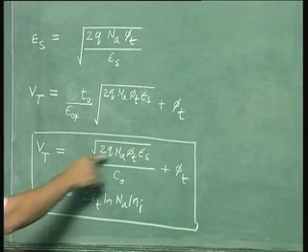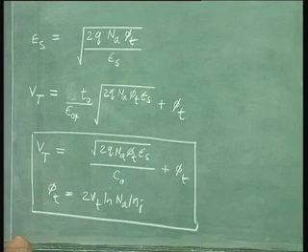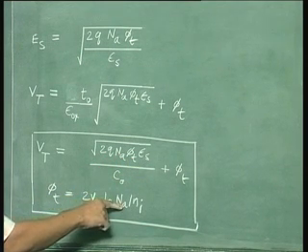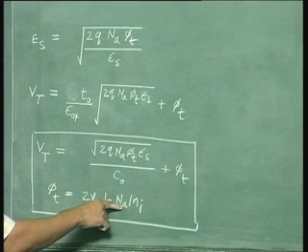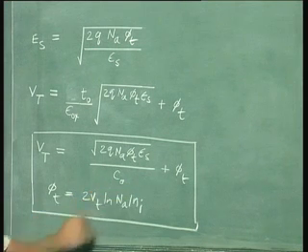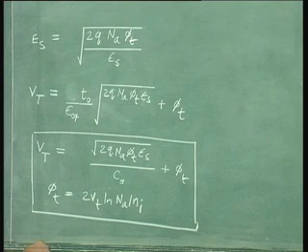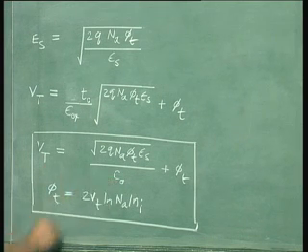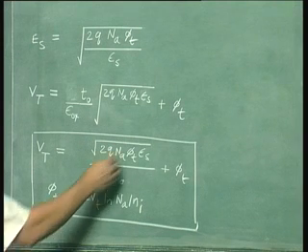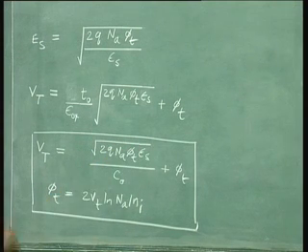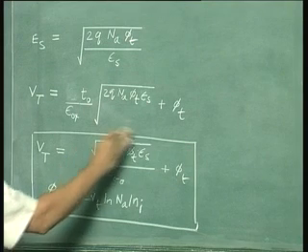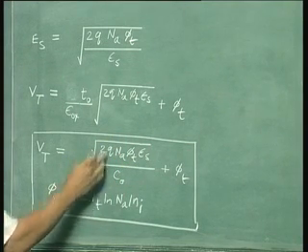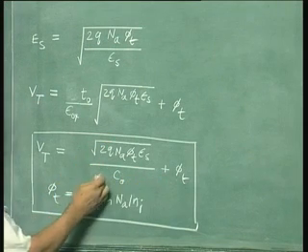We have on the right hand side all the material parameters. So basically you see it depends on the doping level Na, the temperature T because that decides Ni and Vt, and the oxide thickness which decides the C naught. Of course you also have the dielectric constants coming in there. Now in this form you can identify the particular term, the first term on the right hand side, that is this term,